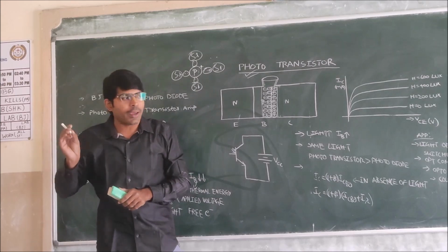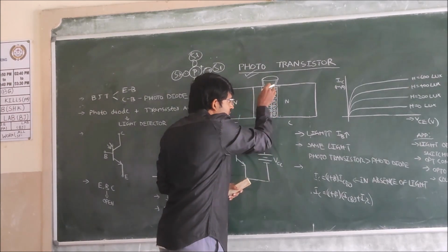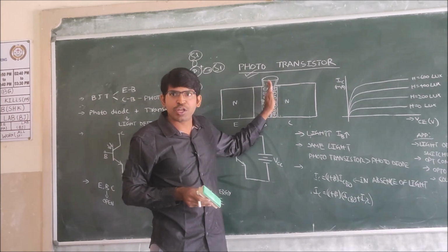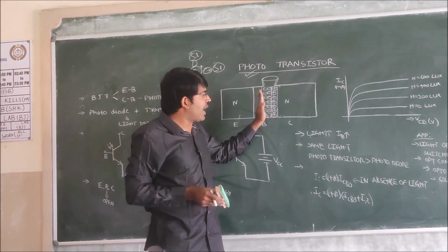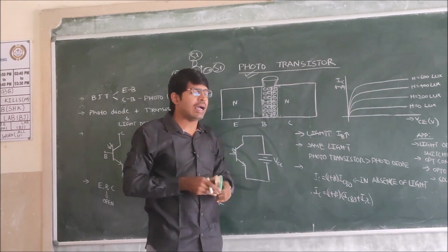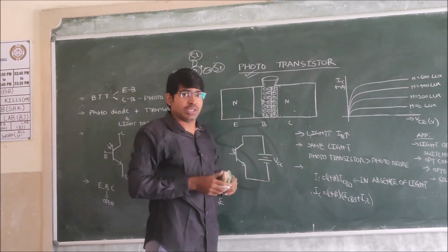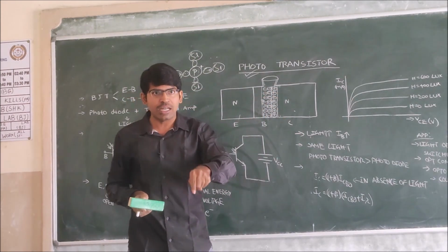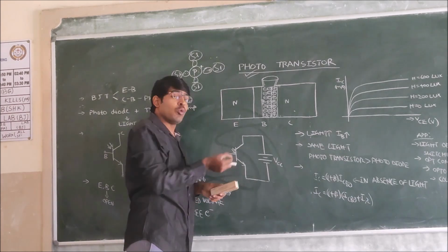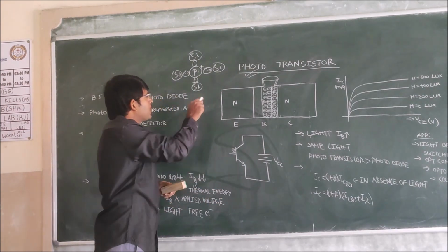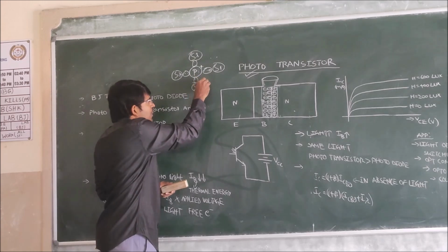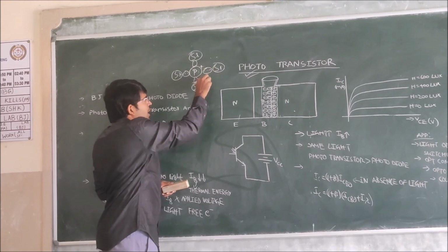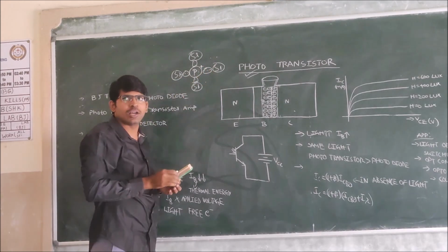Because the negatively charged region is on this side, like the negative terminal of a battery, the electrons will be repelled to the N region. And similarly, the formed holes, even though the hole is an imaginary particle and its movement is an imaginary concept, we say the electron is coming here, replacing this one, and then we say the hole is moving from here to here.